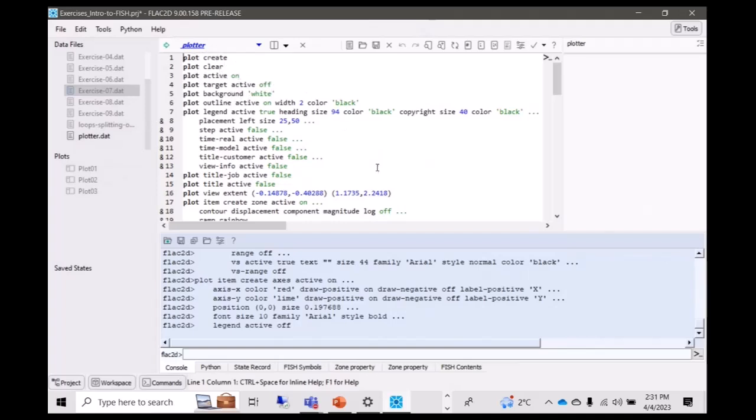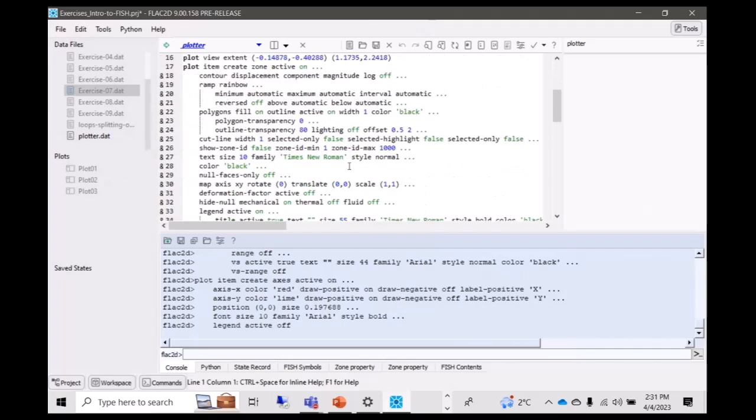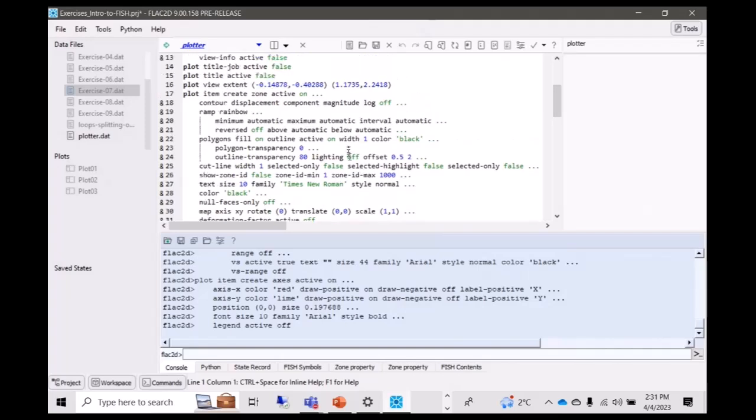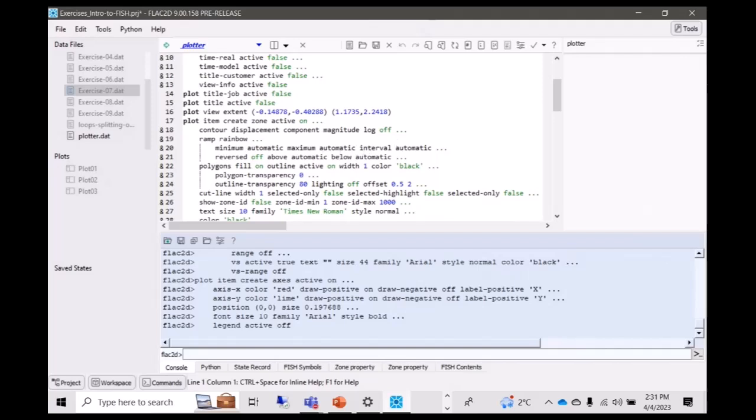Every command and every setting that was used to make that plot, which I just interactively drew, I added the history, I added the zones, I picked what I wanted to plot on the zones, those are all there. And you can adjust them because they're all variables. So you could rotate the view. In 2D it's probably not that interesting, but you could imagine in 3D, you could say, run it with this angle, rotate it 12 degrees, run it.